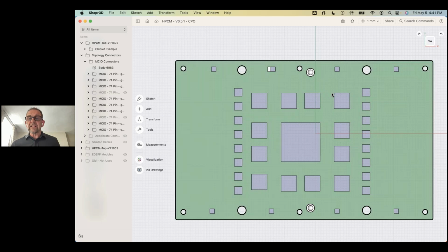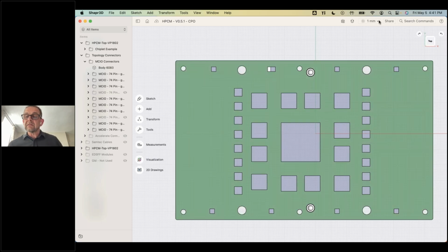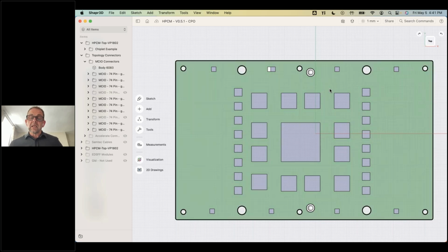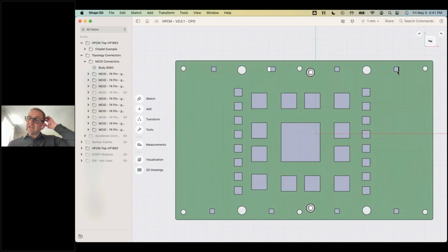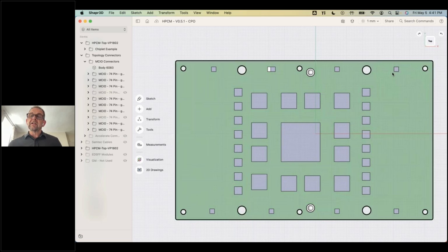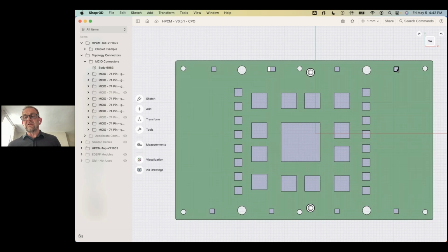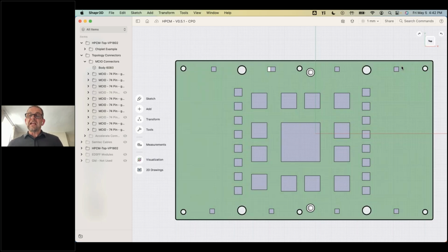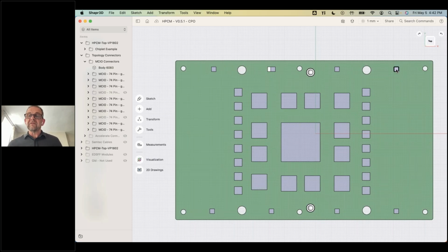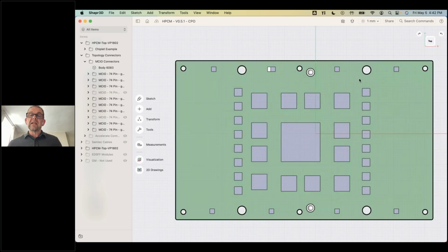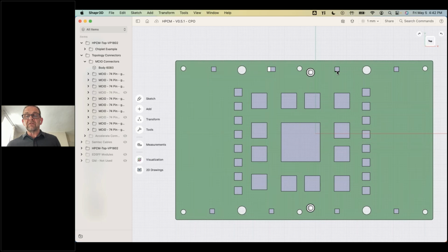Here we're looking at the actual model. I can reduce this down a bit now. There you go, that's better. Here we can see the overall module, and here's the top. This is the electrical one, because it's flipped over. This may be your little IO chiplet that's directly below the connector, with less than a dB, and then you've got another 29 dB for the cable itself. The cable's very efficient compared to PCB routing, so you could probably get many meters of distance even on the thinnest gauge cable. Then we've got another electrical one here, but with a near packaged optics active optical cable plugged into it.